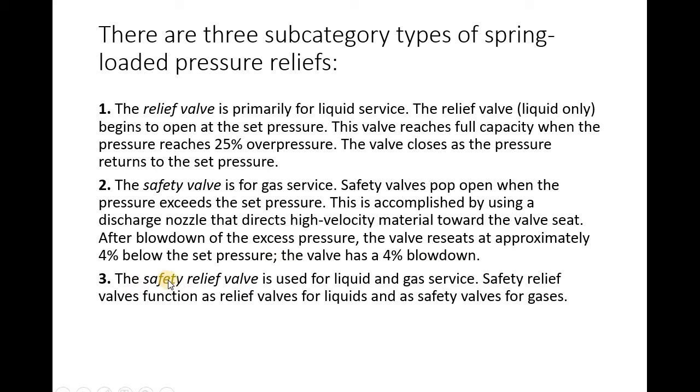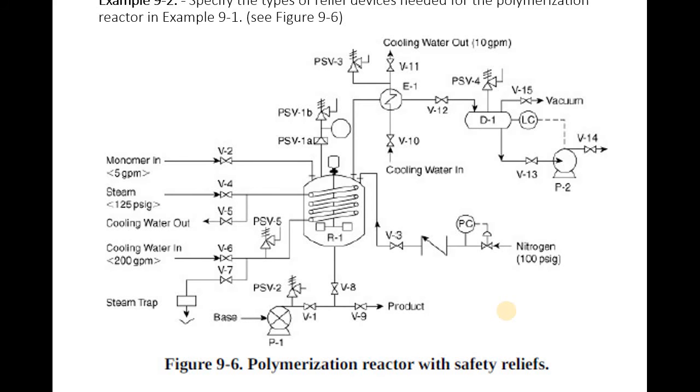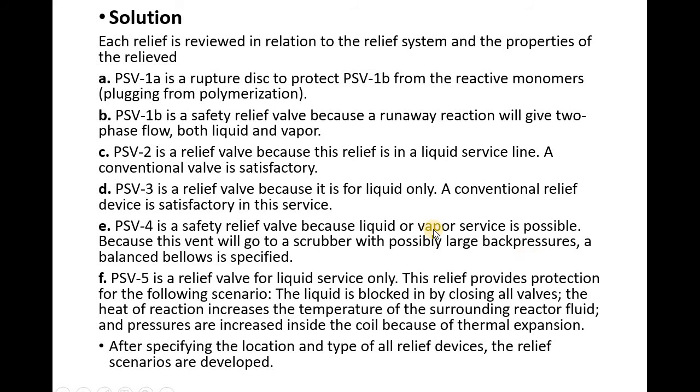The safety relief valve has both words, safety relief. So we can say that's for liquid and gas. Safety relief valves function as relief valves for liquids and as safety valves for gases. It works for both, and this is why we always use safety relief valves. And now you go back here and see what we have. The same example, the relief valves, the safety valves, safety relief valves that we have all over the place.